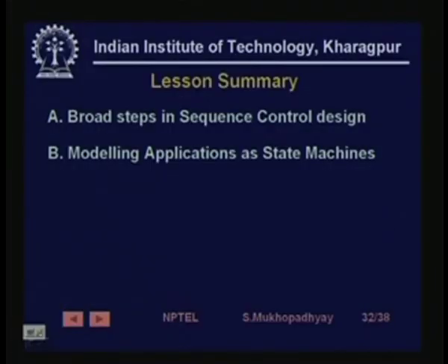So, first maybe write the operation in crisp steps in English, and then try to convert this description of steps into some sort of formalism. And in this lecture, we have seen the formalism of sequential state machines, which can be programmed using a sequential function chart. So, we have seen how to model a particular application.